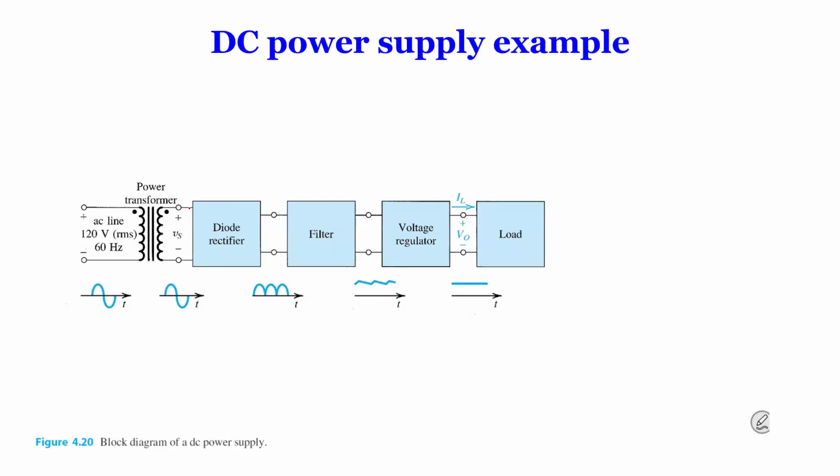But for power supplies, when we get power from the wall, we have 60 hertz AC, but almost all electronics use DC. How do you get DC? Rectified. Whether it's your phone charger, laptop charger, or a television at home, in industry we use diodes as rectifiers to turn AC into DC.